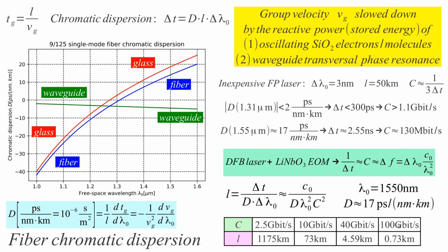Now, the most stupid solution is to do wavelength division multiplexing. We divide this capacity over several links having a lower capacity. So if we divide this 100 gigabits per second into 40 wavelengths having 2.5 gigabits each, we could reach easily 1000 kilometers.